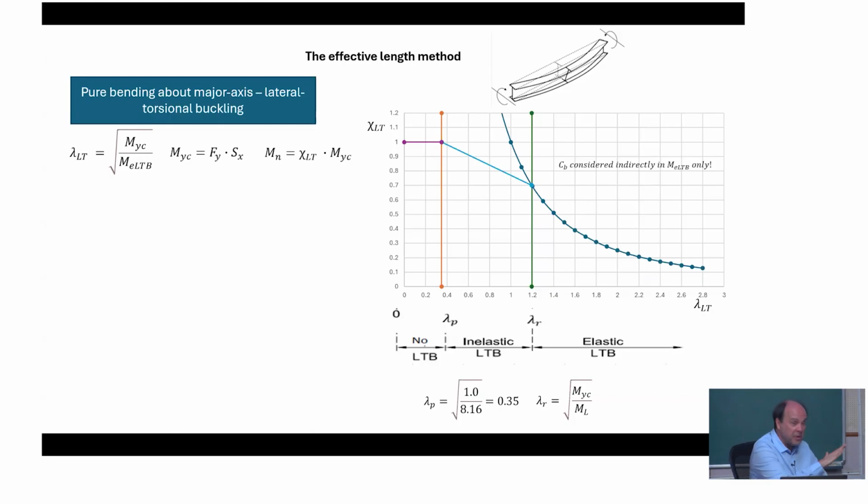But here we assume that Consteel cannot take that into account, because Consteel does everything automatically and reads everything from the linear buckling result. It doesn't have this additional artificial, human type of thing, like what is the member length? We don't know. We just saw with the example that the member length itself is not always the physical length.